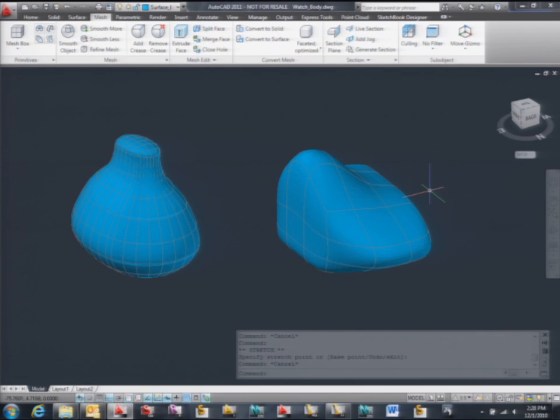The bad thing about mesh modeling is that it's not precise, because you see smoothness, but actually it's interpolating between planar faces, right? So what you see as a curve is probably a set of facets. So for construction, that is not great. But for rendering, I know Toy Story, which is when all this started, you could not render a cylinder. You had to render, I mean, the least amount of faces, the better. Then it's better to have this kind of definitions in which it looks like a curve, but it is not.